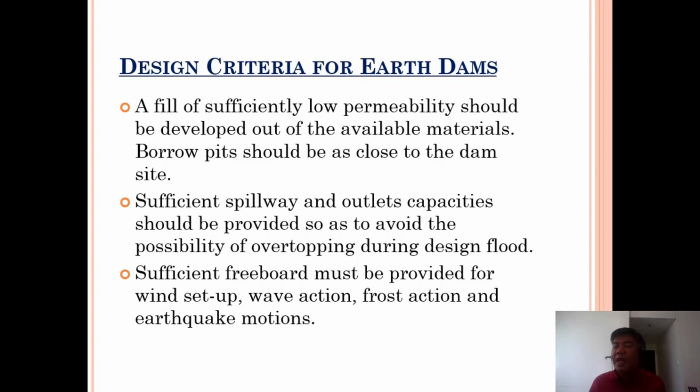So we have to be careful in computing the maximum height of water in the upstream side. Then sufficient freeboard. You have to decide what value of freeboard you are going to provide. In this case, you are going to consider the wind setup, the wave action, the frost action if you are in a frost area, and of course earthquake motion. Another one that will not be tackled in the analysis is the dynamic analysis.